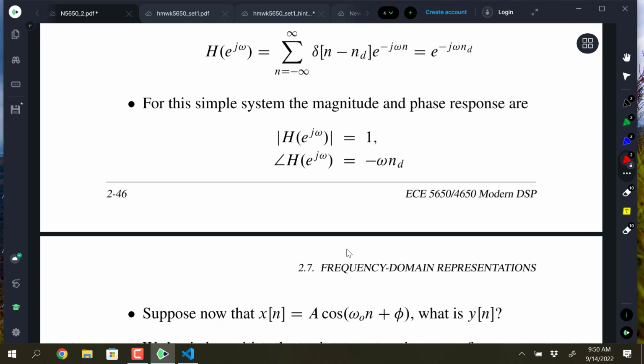But an ideal lossless transmission line is an example of a system that approximates this. It's not a discrete time system, but it has a pure delay of tau_d seconds, and it produces a linear phase and a gain of essentially 1 when you normalize it in a, say, a 50 ohm impedance environment at the sending side and the receiving side.